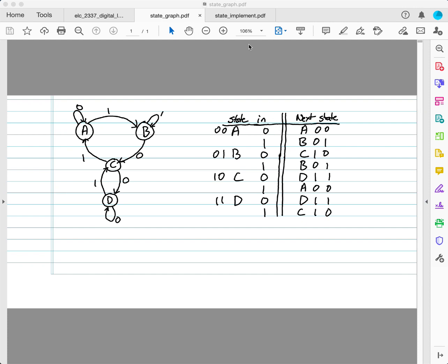Now, let's say we want to do an implementation of this. So maybe I want to do this with Karnaugh maps. Then I would have state 0, 0. So this would make a table, right? 0, 0, 0 is the first row, 0, 0, 1, 0, 1, 0, 0, 1, 1. By having the gaps and everything in here, it's almost nicely set up for a mux design. We're going to do a Karnaugh map here, and we'll put these 2 bits along the top line of it, and we'll put that one on the side rows. But you can nicely set up.